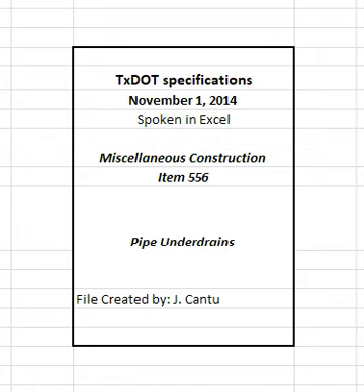2.1.3 Type 3. Bituminous coated corrugated steel pipe conforming to the requirements of Type 1 and uniformly coated inside and out with a minimum thickness of 0.05 inches of bituminous material meeting the requirements of Table 1 when tested in accordance with ASTM A849, Material Class A or Material Class BA. Table 1. Requirements of bituminous material. See table in specifications.